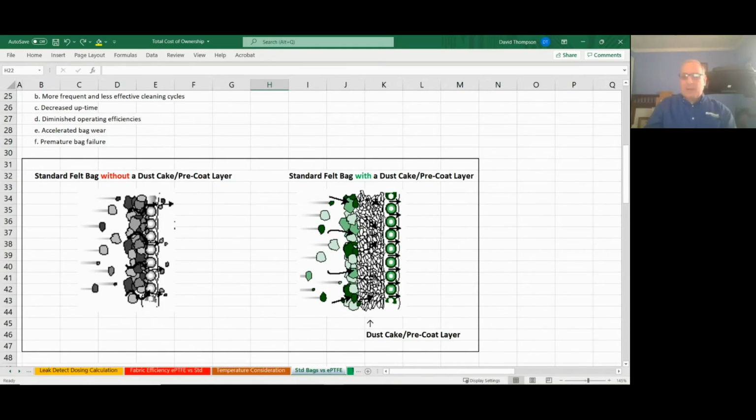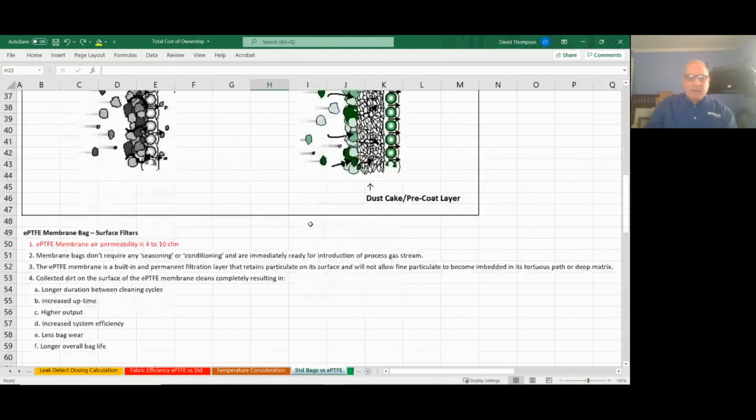However, it takes longer for that to happen. This pre-coat protects it. It blocks it. High differential pressure will push some in there, but typically it can stay on the bag. You can pulse off your dirt and then start your system up again, no problem, without having to reintroduce more. If you're pre-coating and if you're back pulsing on a regular basis, this will last for quite a while. However, you can get dirt entrained.